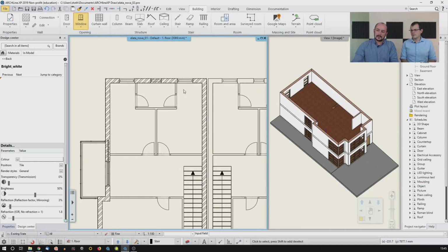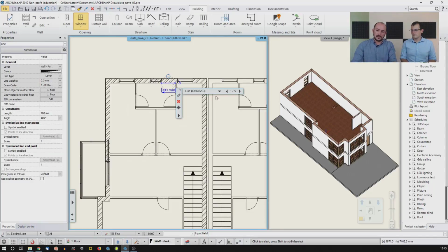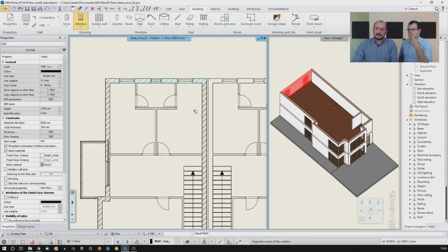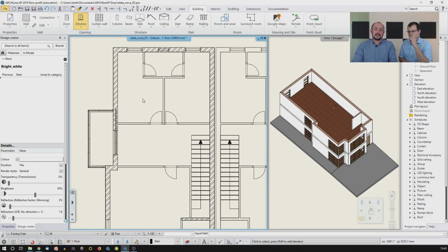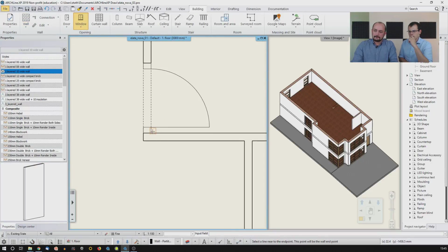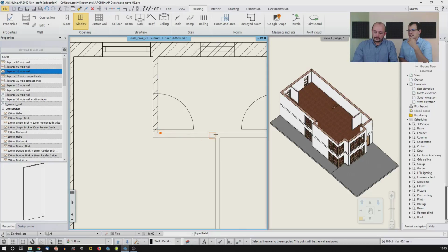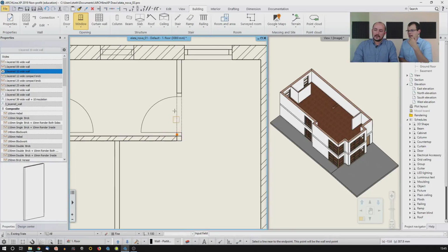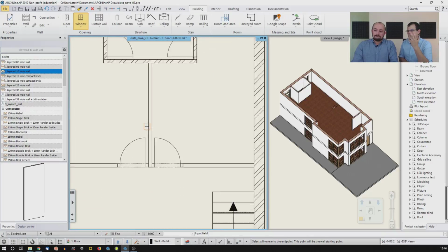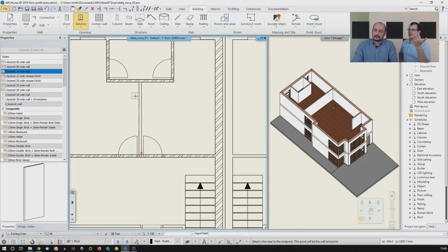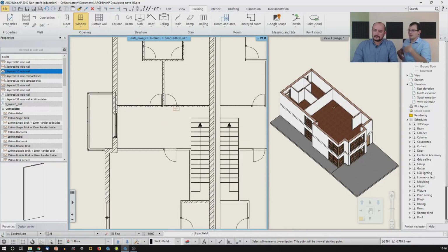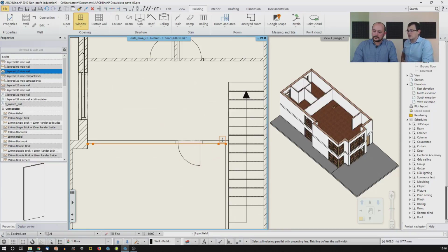So now the walls that I copied from the previous floor and the DWG drawing content are merged together on this floor, and I can use it the same way I used it previously. I just use the walls on the DWG drawing, and I just start processing. So basically you repeat the same steps as you did on the ground floor, only this time it's going to be on the first floor. And this is a good method to keep track of what you have to adjust and what you can just copy. So I think what you showed is a very good practice: you copy everything and then you just decide what you have to get rid of.